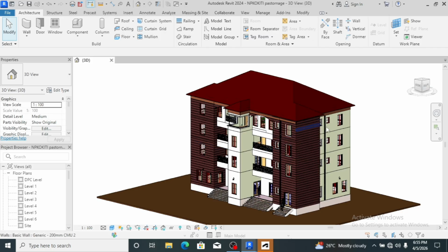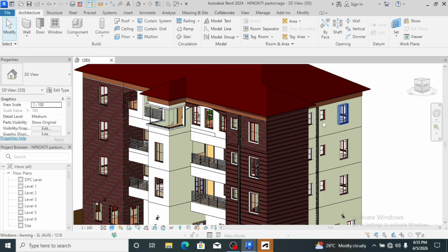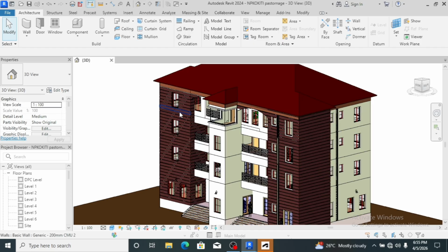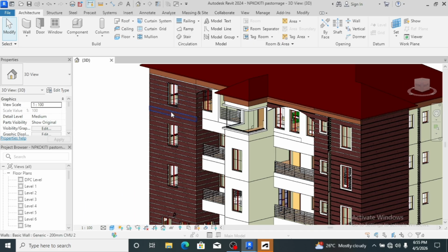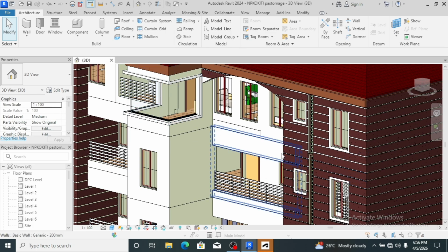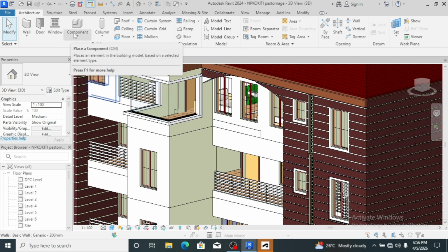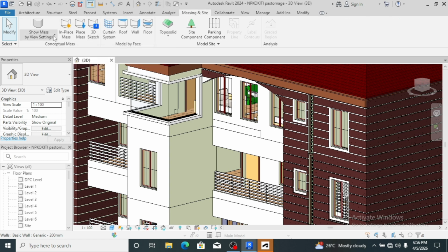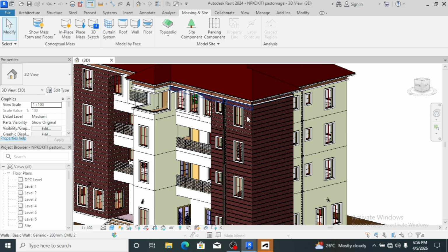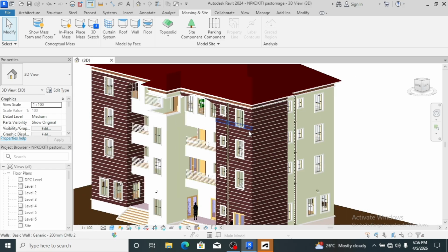We are here once again. I just opened this page for the first time. This is the design we've been dealing with since. Let's open it for the first time. If you notice, the massing product is not on. None of them is on. It shows that it's not showing. You need to go and turn on massing. Put it on. Okay. Now all the massings are showing. All the skirting wall, all the window hood we prepared is showing.